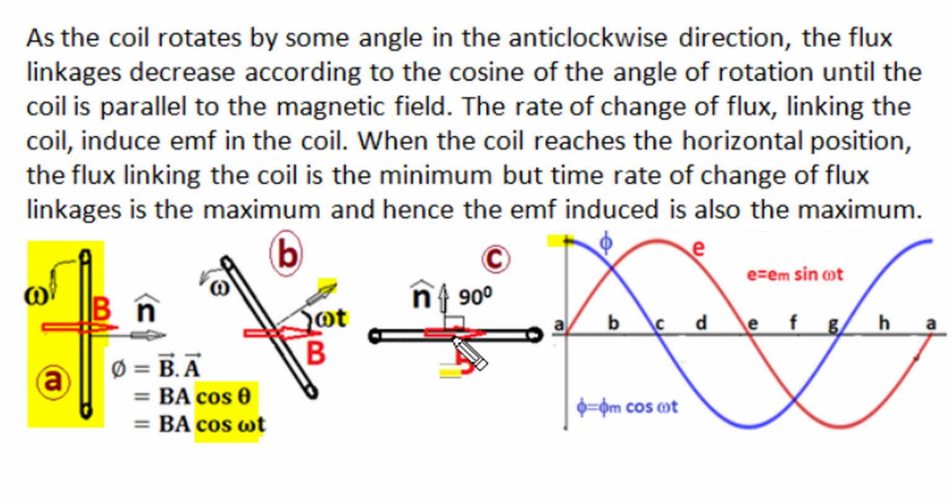In C position, when the rotating rectangular loop becomes horizontal and its plane becomes parallel to the magnetic induction, the area vector and the B vector have a 90-degree angle, and cos 90 is 0. So no flux will cross or link with the loop, and at this C position the flux linking to the rectangular loop becomes 0. Now in this cosinusoidal variation of flux, initially flux is decreasing at a smaller rate, and later on